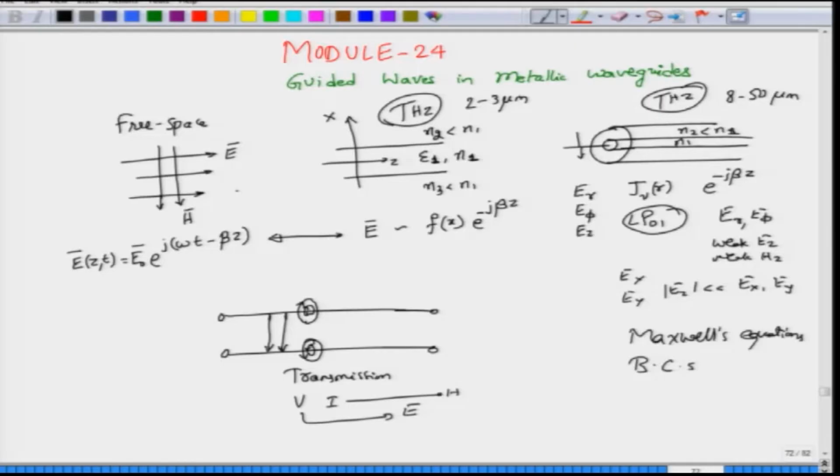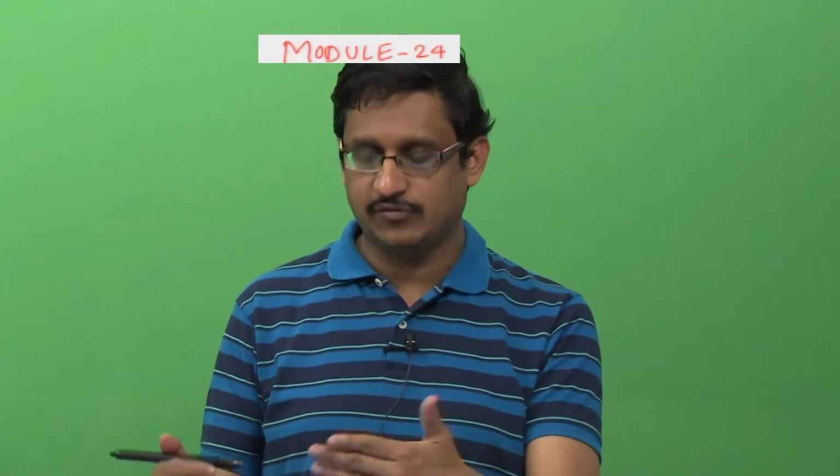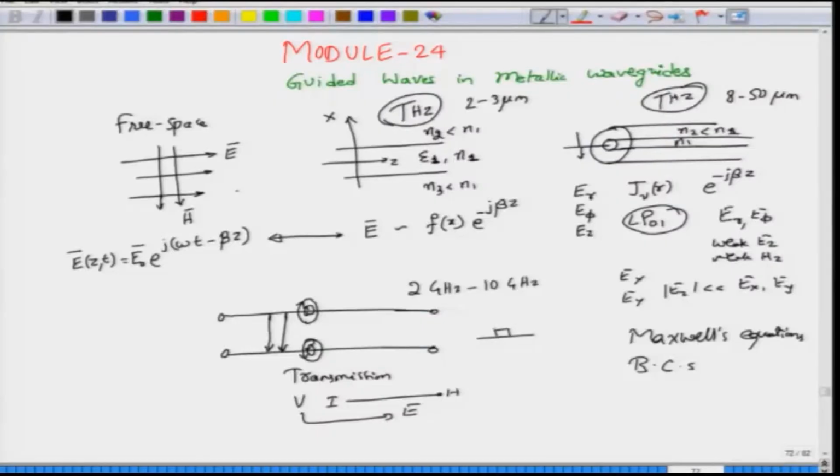The transmission line structures, on the other hand, are good maybe up to about say 2 gigahertz or maybe up to say 10 gigahertz, but again transmission lines are not just a pair of wires, because a pair of wires is good at low frequencies, but as you get to higher frequencies, you for example have to look at the microstrip line, as we have already talked about.